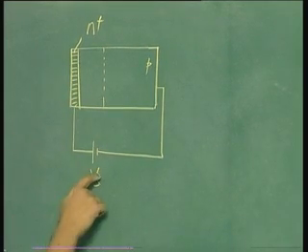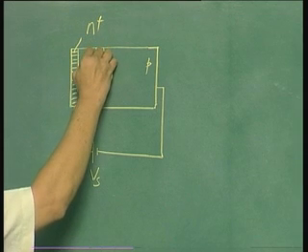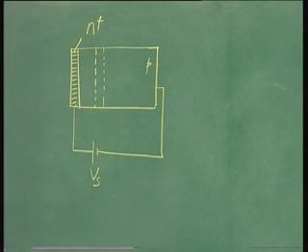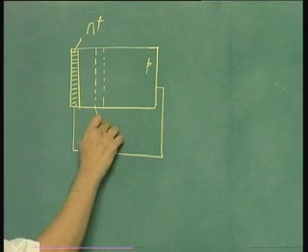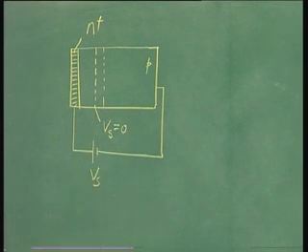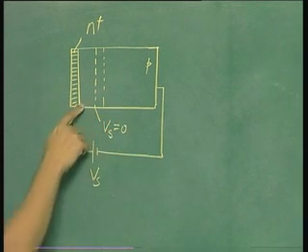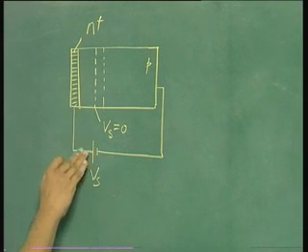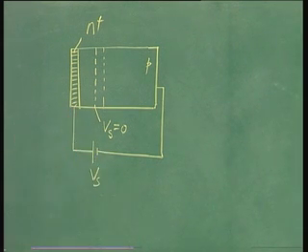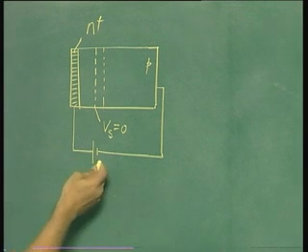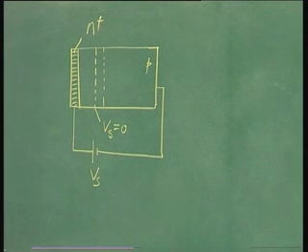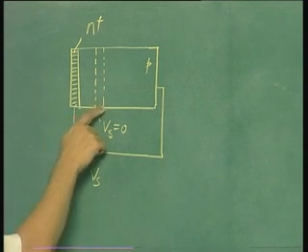So for Vs equal to 0, your depletion layer was something like this. So this is for Vs equal to 0. This was the depletion layer when you didn't really connect the power supply Vs to the N plus contact. So when you connected this Vs, then the depletion layer obviously will increase. In other words, this results in an increase in the depletion charge.